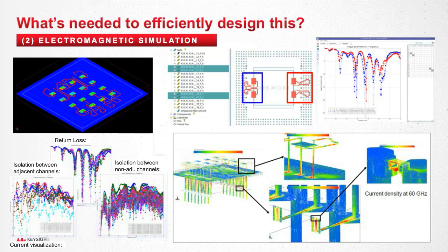On the top here, we're only looking at those antennas now, and we want to figure out how well matched they are in terms of phase. Are we getting a similar response across there? Because if you have small differences between these antennas, that can really affect the side lobes in your antenna patterns.